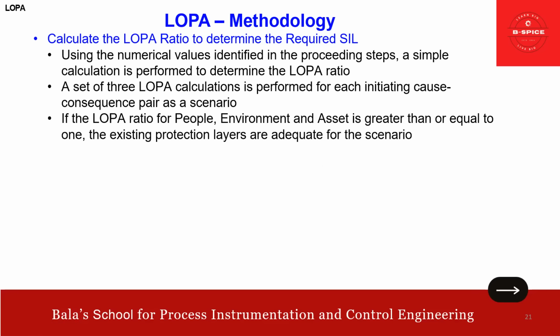But again, you are not doing it manually. You have your automated sheet actually. For every LOPA, you have a sheet. For example, in my case, I did it using one tool, Exelentia. This was provided by exida, Exelentia software, wherein we can do this LOPA. All the calculation is inside, so you don't have to worry. The point is you need to remember the concepts.